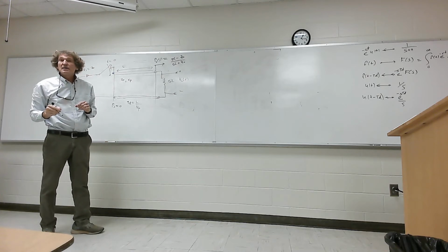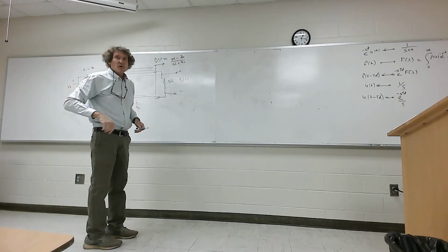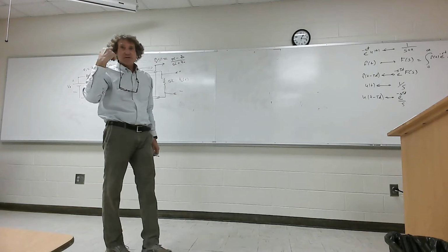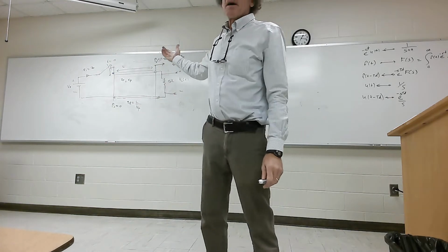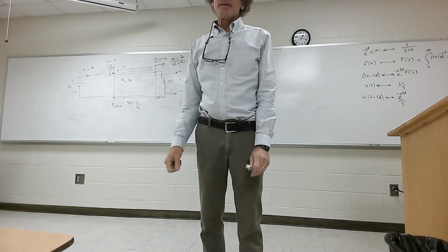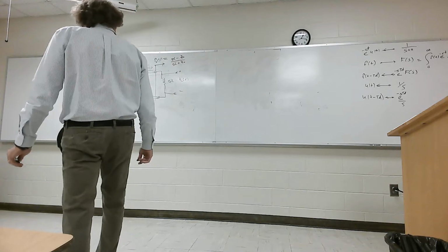Oh, we're gonna make a TL, like we did with TC in the last one. That's right, you're exactly right. We're gonna get the time constant. Why did I do that, by the way? Well, remember RC circuits? What's the time constant? R times C. What's the time constant there? Z naught times C, really an impedance times the capacitance. It's the rate of charge.